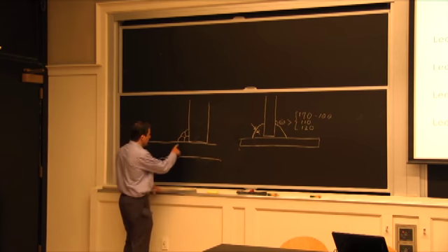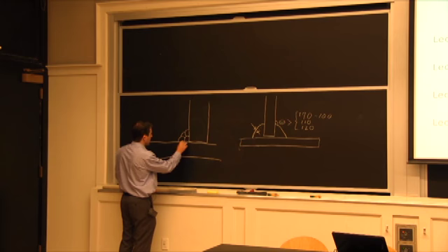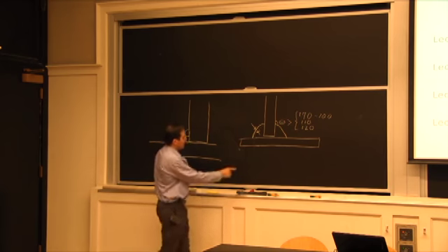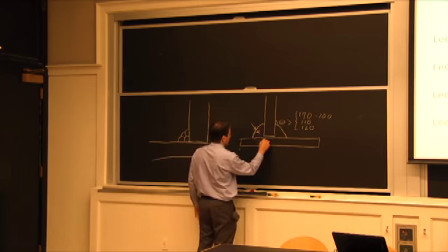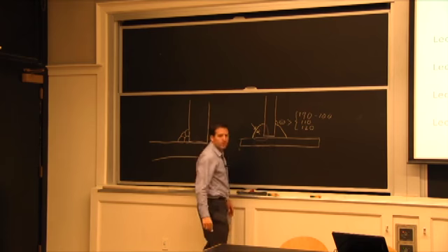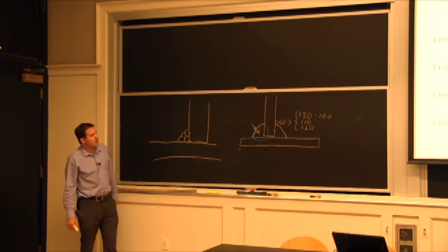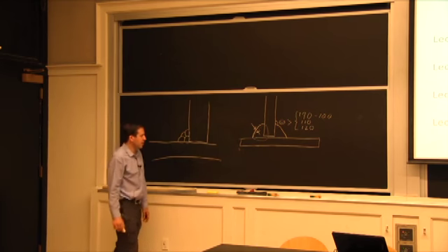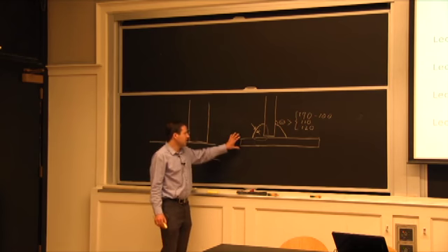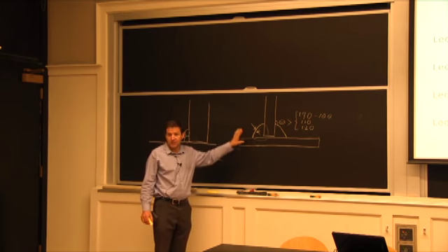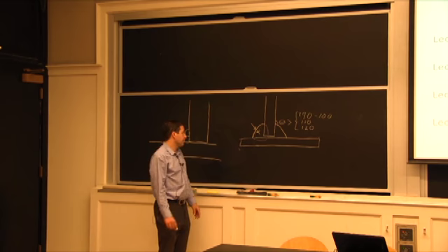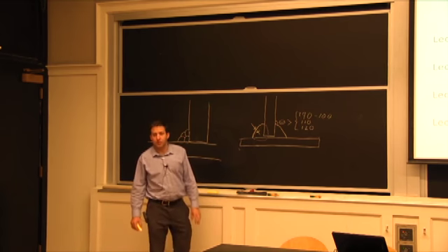When you're not fused, this is a situation where fusion will be very limited under these beads. There'll be a little bit maybe in the middle of the bead. Whereas on a weld like this, you expect to melt this whole area to make the connection. So I just thought, in terms of when we were talking about the capacity, I'll mention the inspection as being a specific aspect to call for when you're making a design.